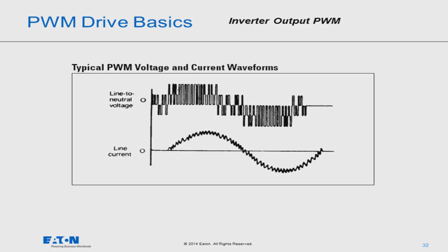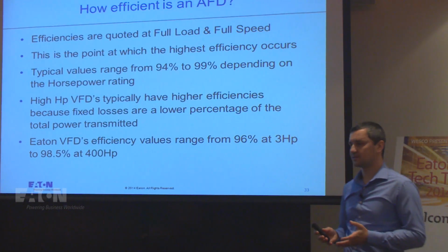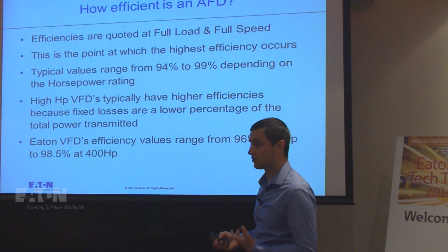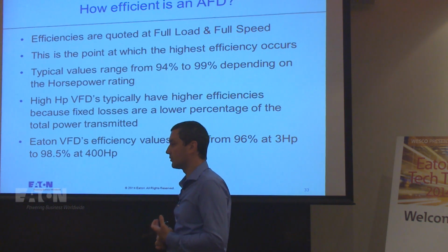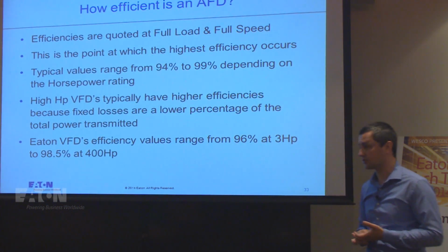How efficient is your VFD? They're pretty good actually these days. And the amount of losses that you have on a VFD is very small compared with the savings you're making in energy by using a VFD, okay? Why do you have some losses in the VFD? Because we have all kinds of electronics involved, okay? We have some resistance in there that is just going to burn off some of the energy.